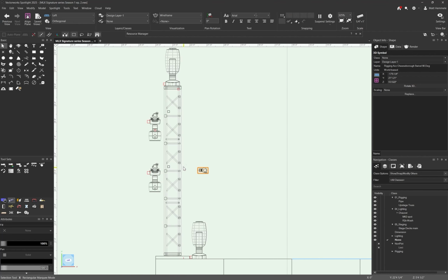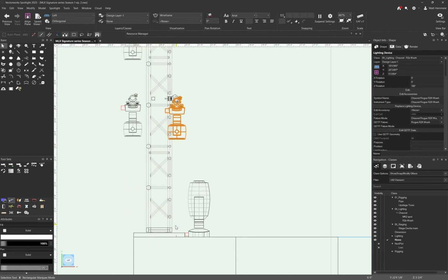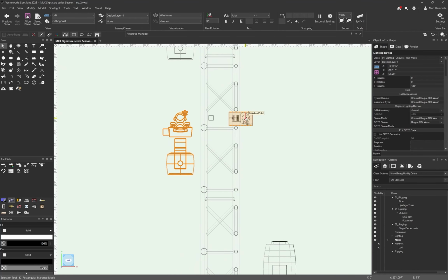So what we want to avoid is saying, oh, okay, we're gonna put this here, we're gonna put pipe here, and then we're gonna put basically a fixture here. Well, that load, yes, it's above where the base is, but it's on the front end of it. So as that thing moves around, all of that movement is happening and it's pulling this direction. So what we want to avoid is front loading or rear loading these uprights.